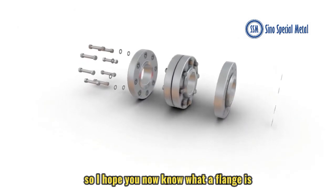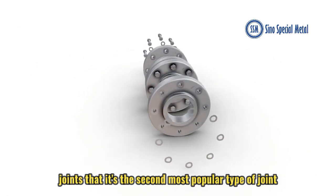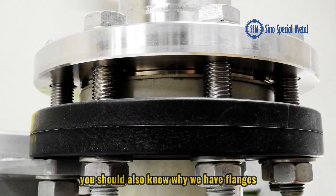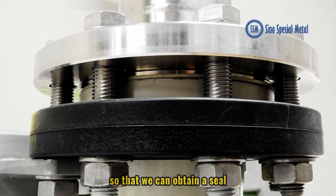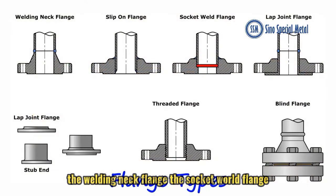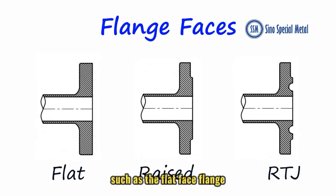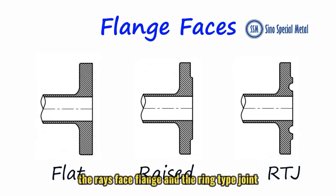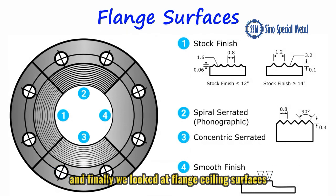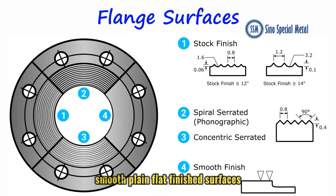So I hope you now know what a flange is. I hope you realise that it's a type of mechanical joint, that it's the second most popular type of joint after the welded joint. You should also know why we have flanges, so that we can obtain a seal. We discussed the different types of flanges, the welding neck flange, the socket weld flange, the lap joint flange, etc. We looked at some flange faces, such as the flat face flange, the raised face flange, and the ring type joint. And finally we looked at flange sealing surfaces, stock finish, spiral serrations, concentric serrations, smooth, plain, flat, finished surfaces.